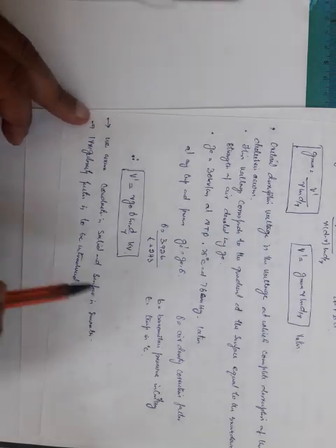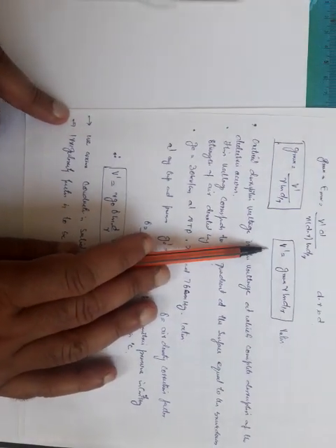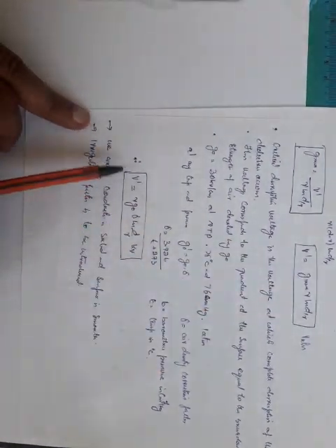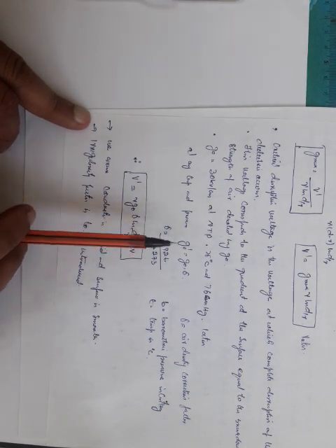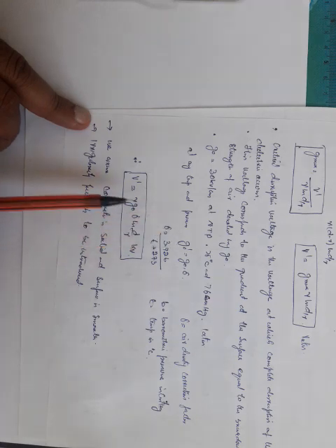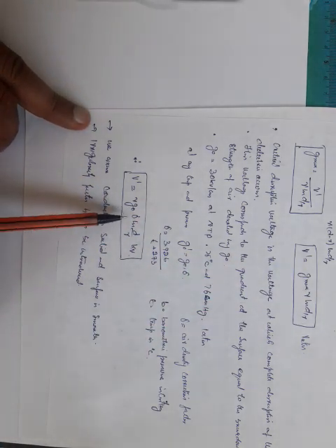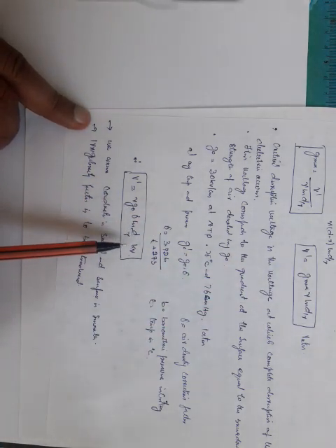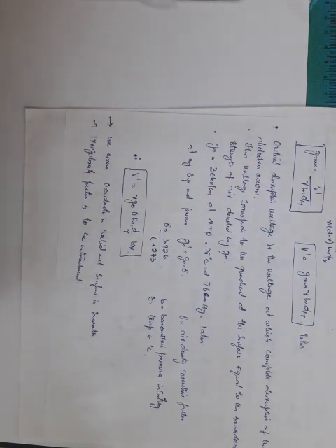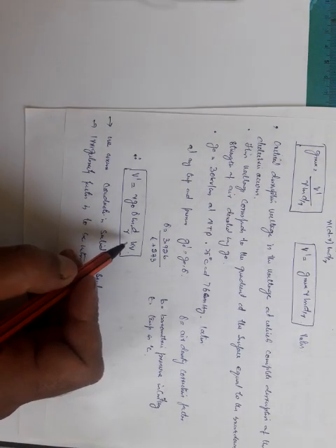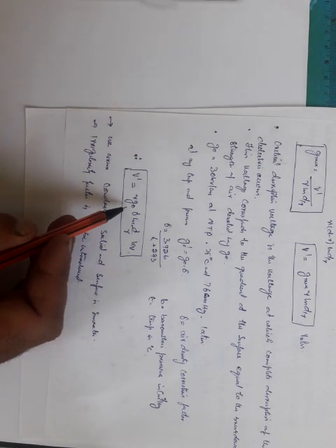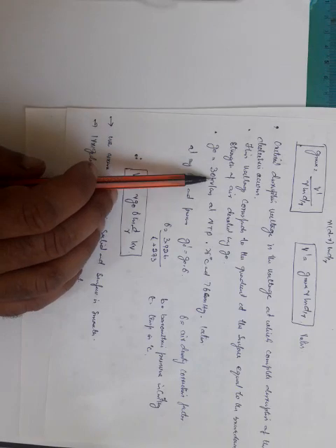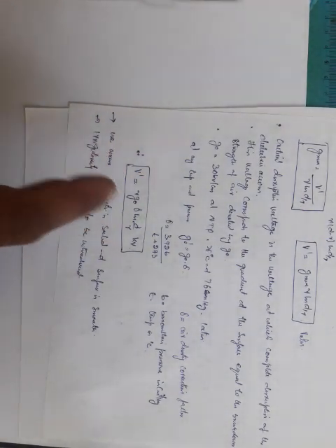So this equation is modified now, V is equal to r G naught dash ln of d by r, where this G naught dash is equal to G max, that is equal to G naught into delta. Now its unit is kilovolt, because you will see that G naught is given in kilovolt per centimeter, that is, the total unit of this voltage will be now kilovolt.